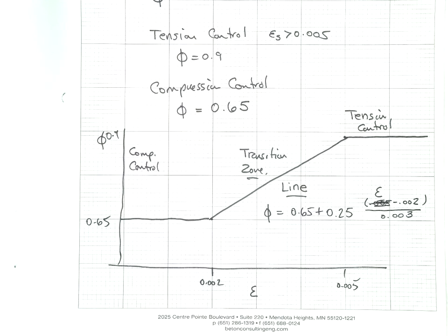So that's load and resistance factor design. We have the resistance factors. That is a number, less than 1, that we discount down the strength for. Conditions we know we understand well, tension control, a little bit of a discount. Things we don't like very much, compression control, a lot of a discount. Either way, we're reducing the strength of the beam so that we can design using the reduced strength beam, and then we'll be okay. We'll have a safety factor built in. That's the first half.